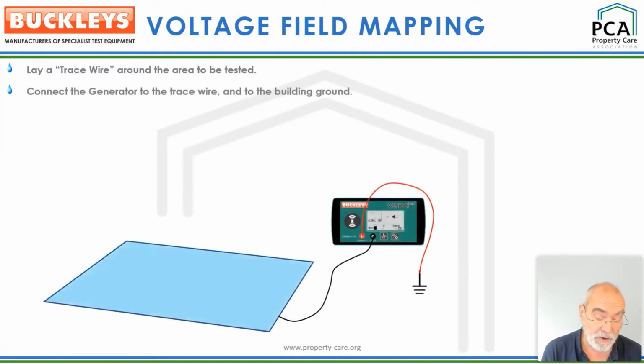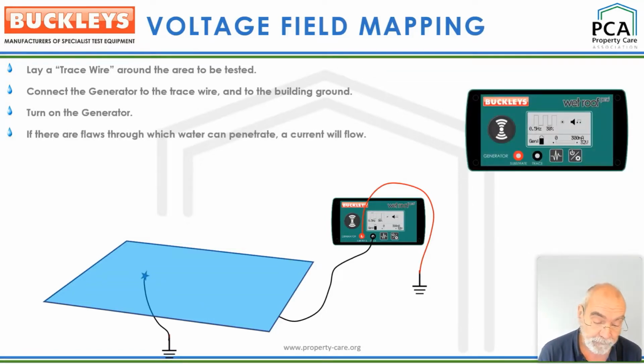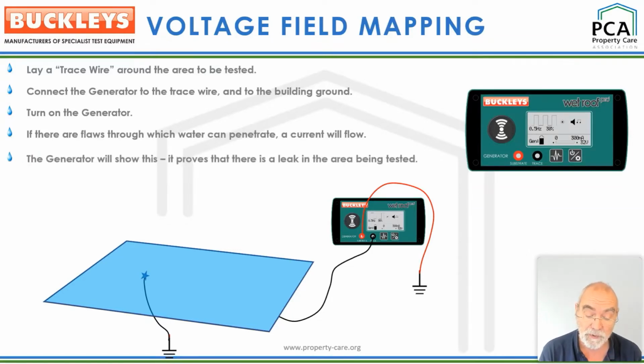With voltage field measurements, a thin layer of water is spread across sections or the whole of the area under test, which is bounded by a field electrode, the trace wire. The generator applies a voltage between the field electrode and the building ground. The technique is applicable to substantially flat surfaces, including decks and roofs. It can also be used on shallow slopes.